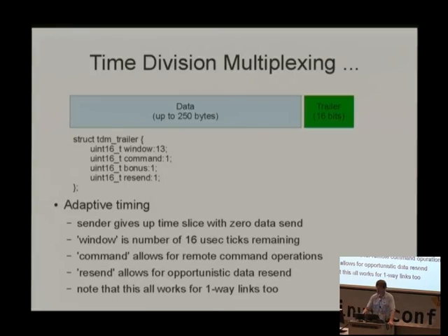And so instead of using acknowledgements for higher priority operations, the ground station, before it sends a packet to say you can take over my time slice now, can resend the last chunk of data with a bit to say this is resent data, which means don't inject it into the serial stream at the other end if you got my last packet. Right?